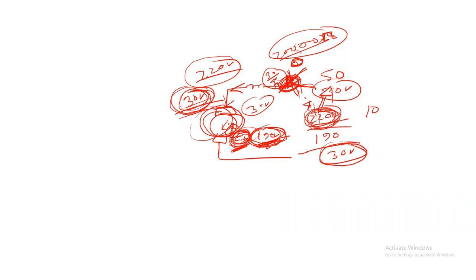At first it is very low, 10 volts, 20 volts, and then slowly your voltage increases. As this voltage increases, your back EMF slowly develops. Then if your back EMF is 190, the full voltage is passing through this section.